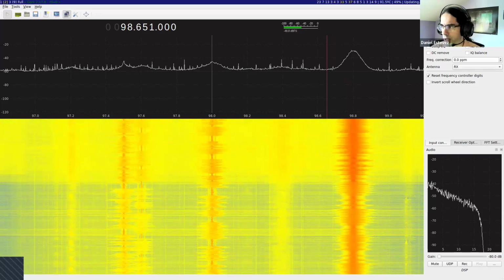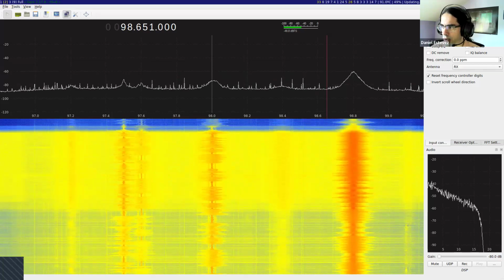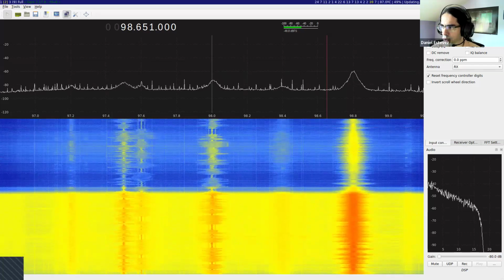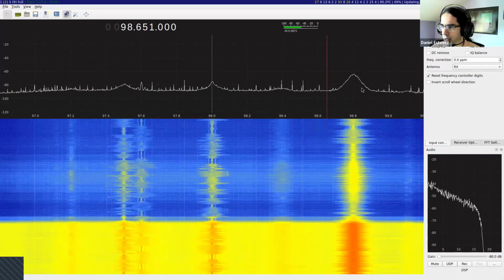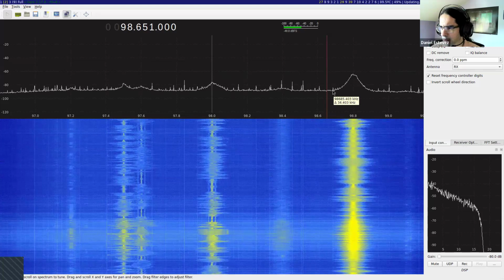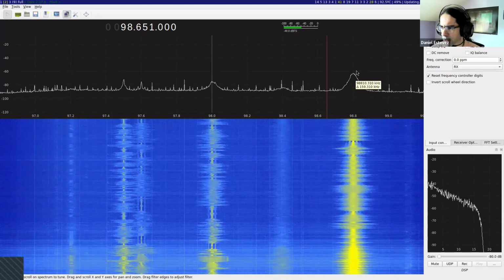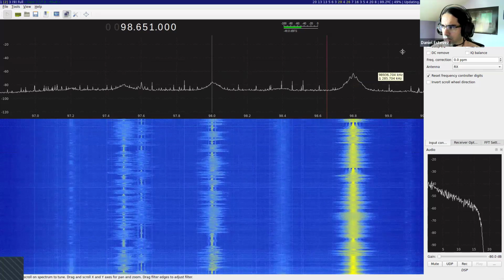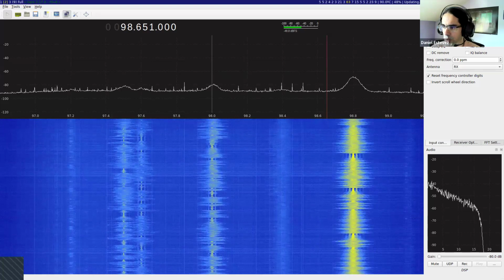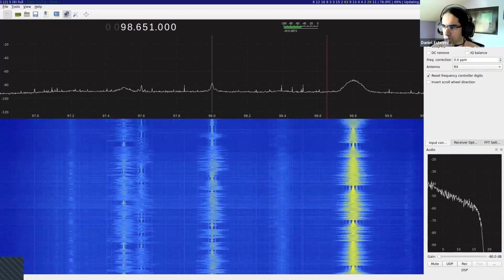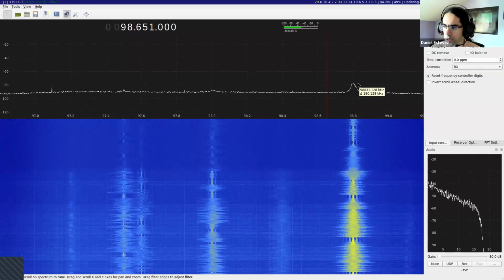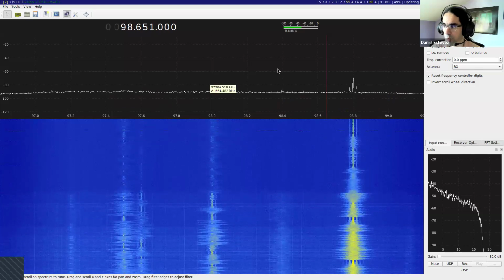So that's one end of the gain scale. We can go to the other end. So I was at 20 before, and then the question we can ask ourselves is, if I go to 10 dB, do I still get 35 dB of signal to noise ratio? And probably not. It looks like I'm getting even less than 30. And the reason for that is the gain now is too low that signals begin to be drowned out. So you can see that if I continue decreasing the gain, the noise doesn't even move, but all the signals decrease in power, and so the weaker of them disappear.